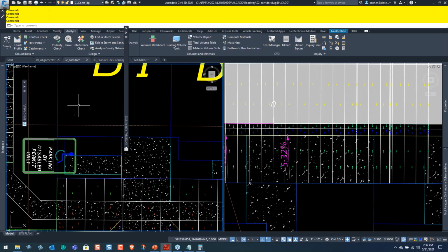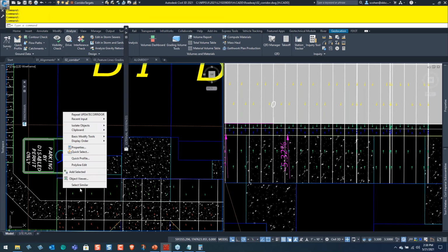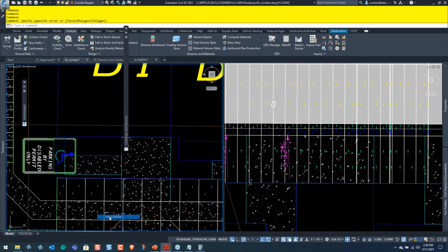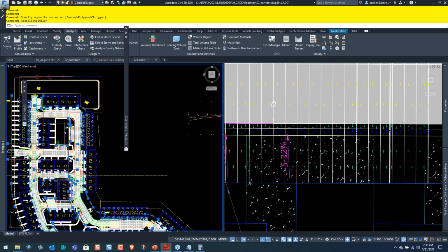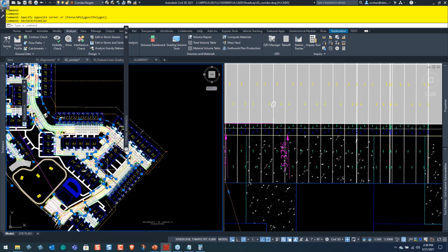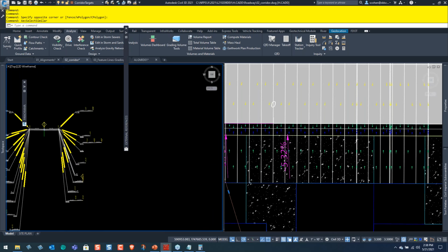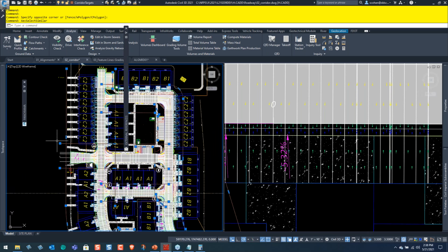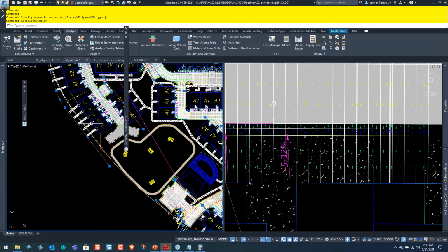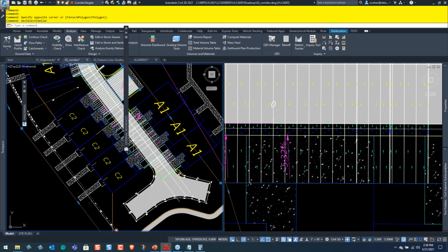So if you look, I'm colorblind, so I might say this wrong, it looks like a brown line. But if I select this one here, it's on a layer called corridor targets. If I do a select similar, you will see that these are simply regular polylines and they're offset along my entire job. I call it a trigger target. It simply turns a specific part of your assembly on or off, right? You simply just know that. And so these are just offset from the alignment. That way I can just pick that, because sometimes your offset alignment will not actually go all the way, and so it might end your corridor targeting. So I just offset some polylines and put them on their own unique layer, okay?